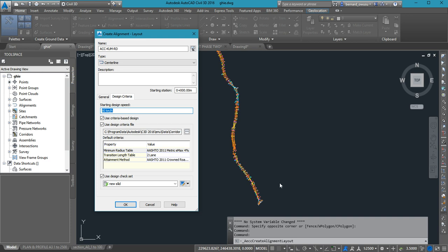I'm saying 60 because this road actually is not Accra Kumasi. It's a regional road, and it's going through settlement and mountainous terrain. So we have to use a lower speed. Do you understand? So let's assume that our design speed is 60. Please, are we okay? Now our design speed is 60.